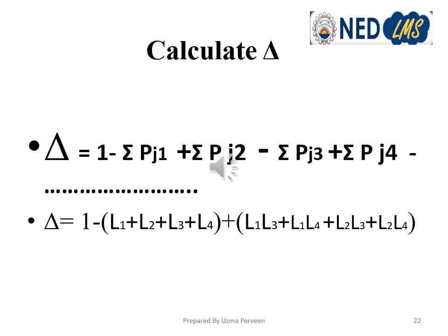We'll put in the values of L1, L2, L3, L4. Please keep in mind that when we calculate the loop gain, for example L1, it is the product of the branch gains. When we calculate the forward path gain or the loop gains, we take the product of the branch gains. Whereas when we use this formula, we use the summation sign for individual loops, either single loops or pairs of two non-touching loops.